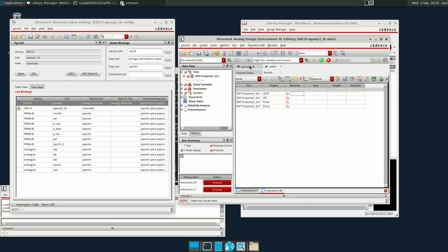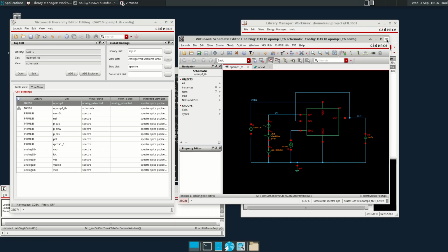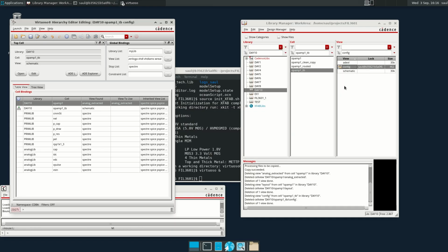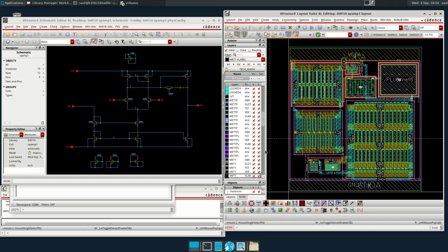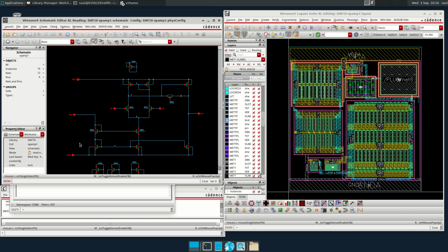Okay, now the very last thing to do is that we have our op-amp here, and very often we have holes in the layout that are not filled, and what we can do here is just to add some extra capacitors to ground, to do some decoupling capacitors filtering the power supply, or some critical net, for instance the biasing, the current biasing.